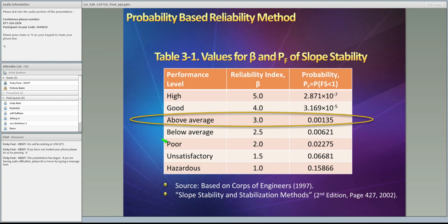So why do we analyze the mean of the bias and the variance of the bias? Because we want to generate a large number of load transfer factors to input into the Monte-Carlo simulation. We're just using these 41 as a base to generate a large number of random etas.